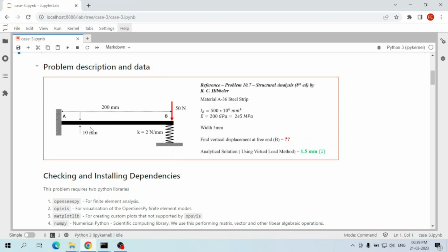But this is not the case with this kind of spring supports. These come under a category called flexible supports because these supports offer only a partial resistance. Hence we cannot put 0, and in fact we don't know what value to put here as stiffness for this kind of supports. This has to be evaluated using the material constitutive relationship.